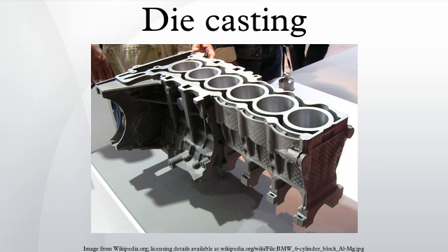Other features in the dies include water cooling passages and vents along the parting lines. These vents are usually wide and thin so that when the molten metal starts filling them, the metal quickly solidifies and minimizes scrap. No risers are used because the high pressure ensures a continuous feed of metal from the gate. The most important material properties for the dies are thermal shock resistance and softening at elevated temperature. Other important properties include hardenability, machinability, heat-checking resistance, weldability, availability, and cost. The longevity of a die is directly dependent on the temperature of the molten metal and the cycle time.